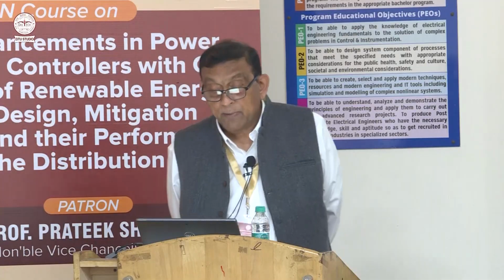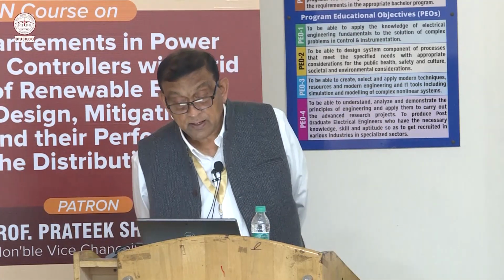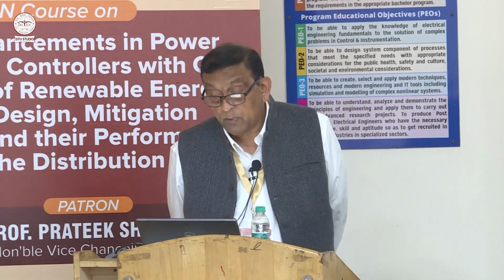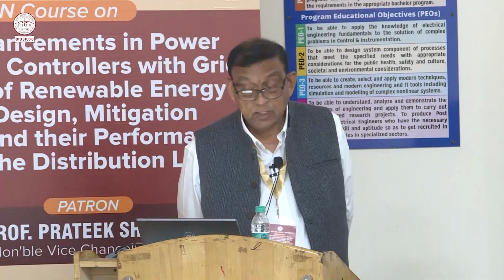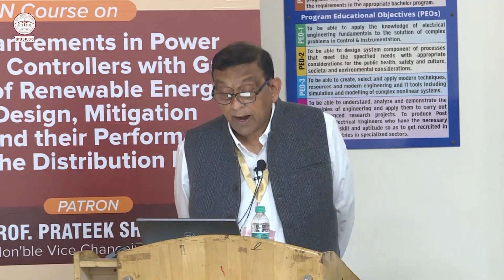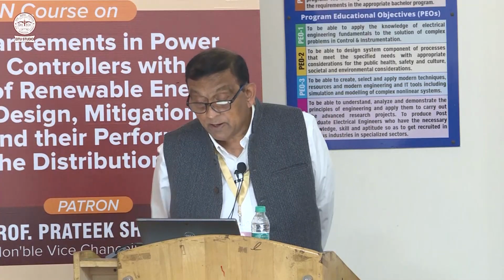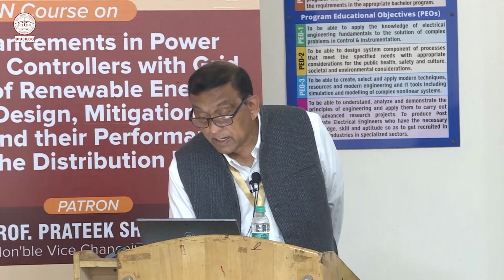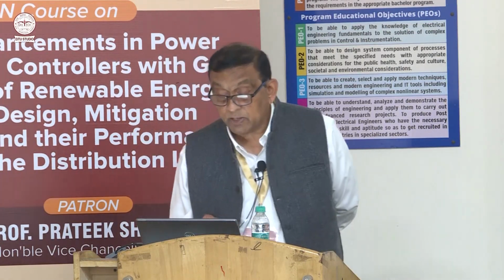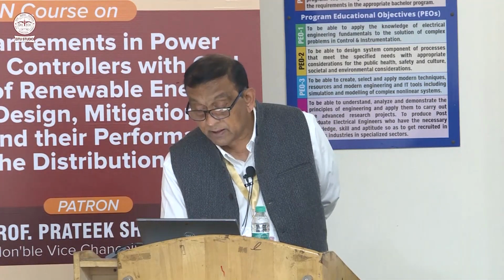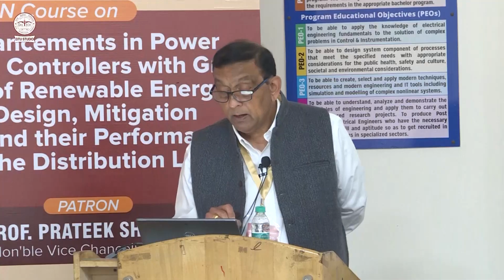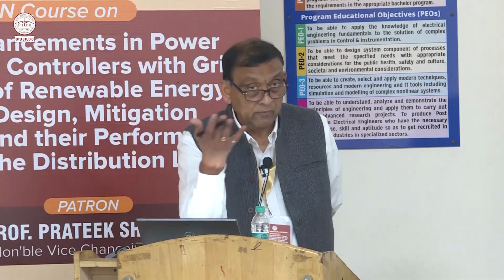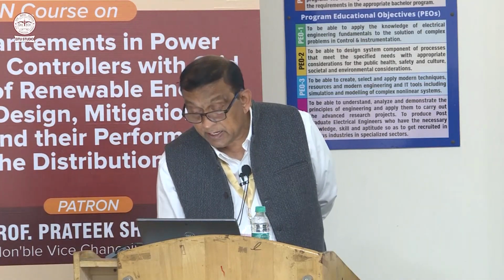If you see the requirements and applications of shunt active power filters, these are current based power quality problems in distribution systems for which we use shunt active filters. So what are the problems? RMS supply current may be high, there might be low system efficiency because of increased losses, poor power factor, poor utilization of the distribution system, heating of components of the distribution system because of the different harmonics, right? And then derating of the distribution system.